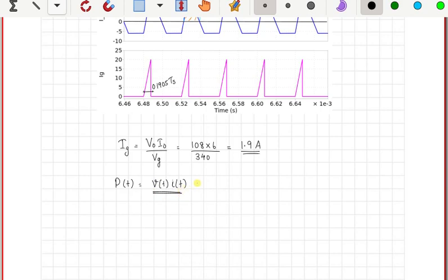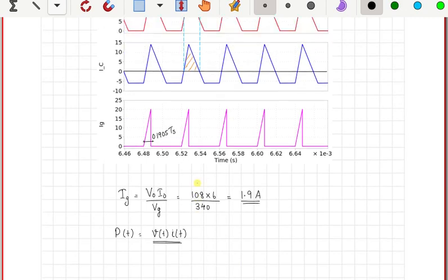So these harmonics then just flow in and out of the source without contributing to active power production, but nevertheless what they do is they will heat up the source. Whatever internal resistance is there in the source, it gets heated up. So these are really unnecessary components, and therefore that is one of the main problems with DCM as well.